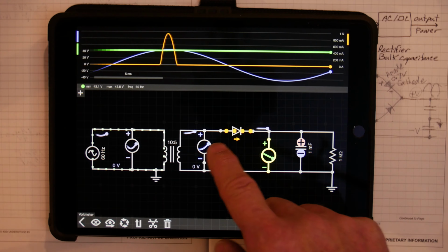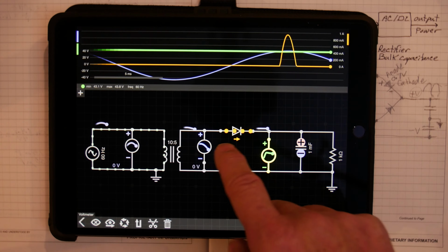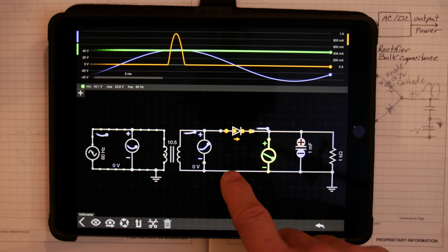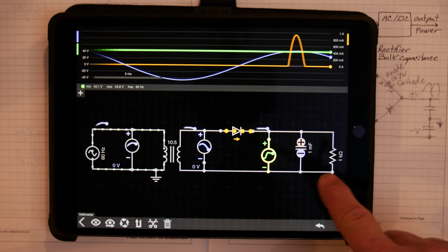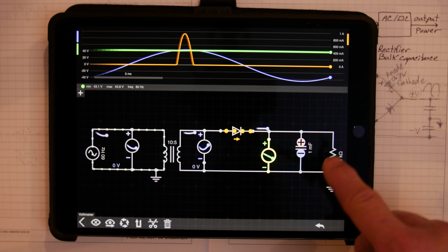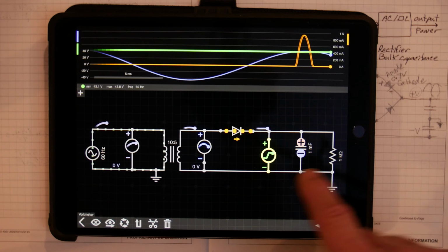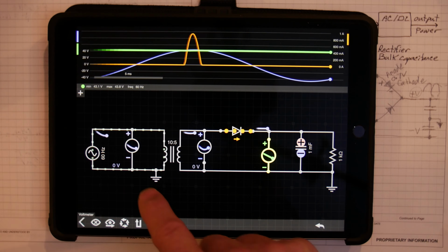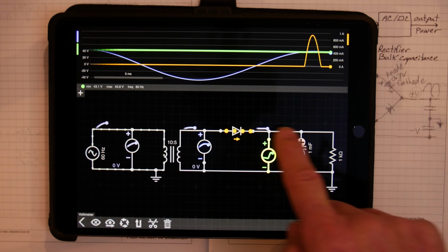Now, by the way, since I only have a single winding on this output, I'm going to have to use 3 more diodes to steer that. Imagine if I had one diode here going the same direction, like this. Current is going this way through the load and back this way through the transformer winding. It's going around this way. It doesn't flow through that ground and go anywhere that way. It just cycles through here because we're isolated from this side. So the current just cycles this way. That ground waveform, even though we're touching here, there's no current flow to that side. It's just all through here.